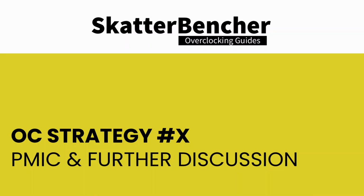In this segment, we further dig into the voltage limitation and chat a little bit about the remaining overclocking challenges. As you've seen from the previous overclocking strategy, even though we've worked around the firmware voltage limitation, there's still a 1.1 volt output limit on the PMIC side. So let's have a look at the PMIC.